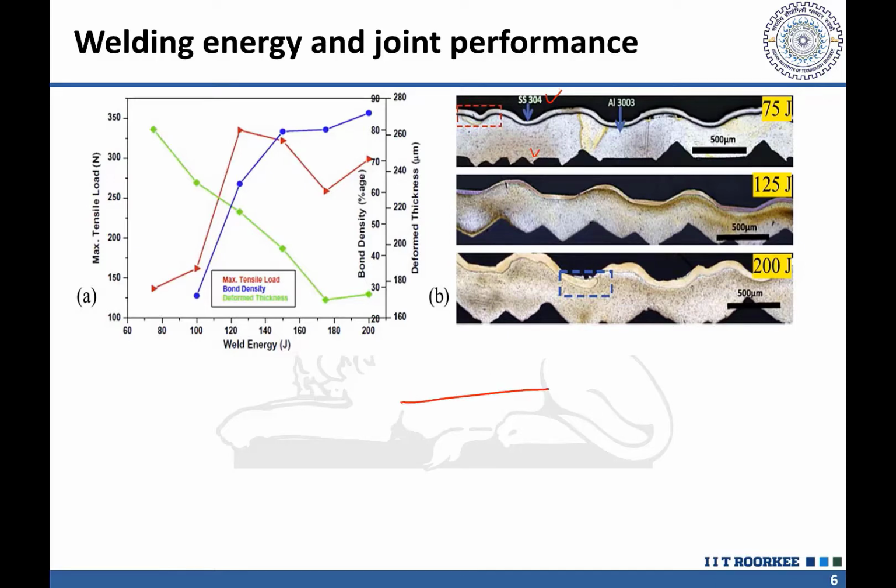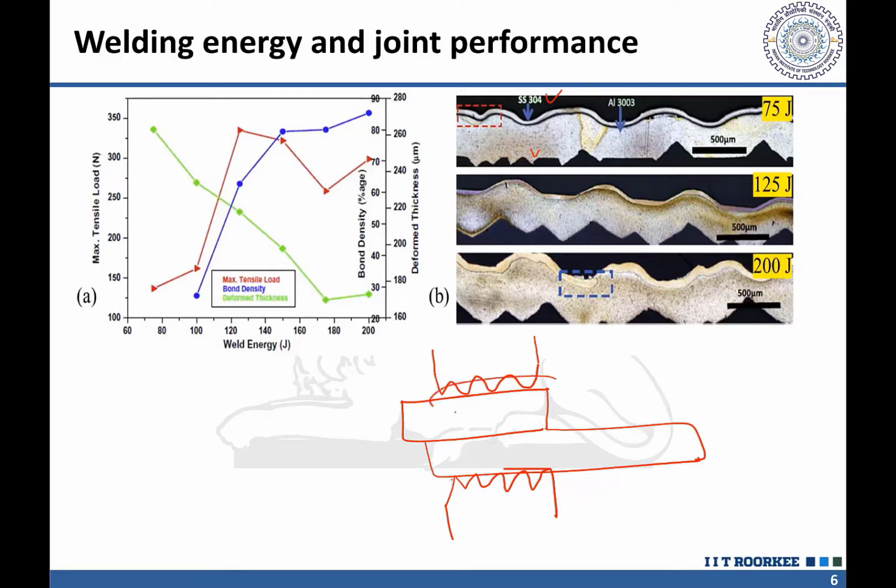So what we do, we take the two components like this, and we apply the sonotrode. The sonotrode has a very typical geometry at the surface through which it is applied, so that you can apply very intense vibration in a localized manner wherever you want to develop a joint. These will be increasing the localized pressure at the surface of the workpiece, on both sides.